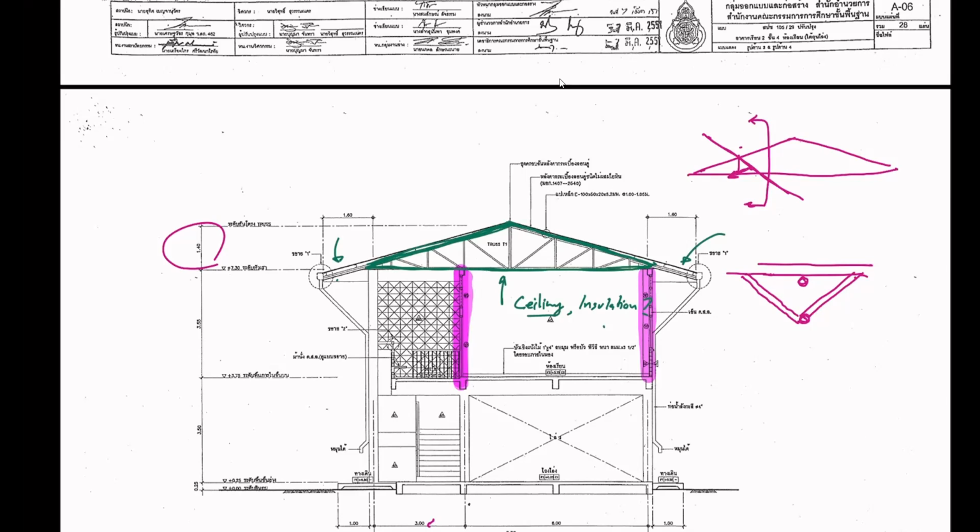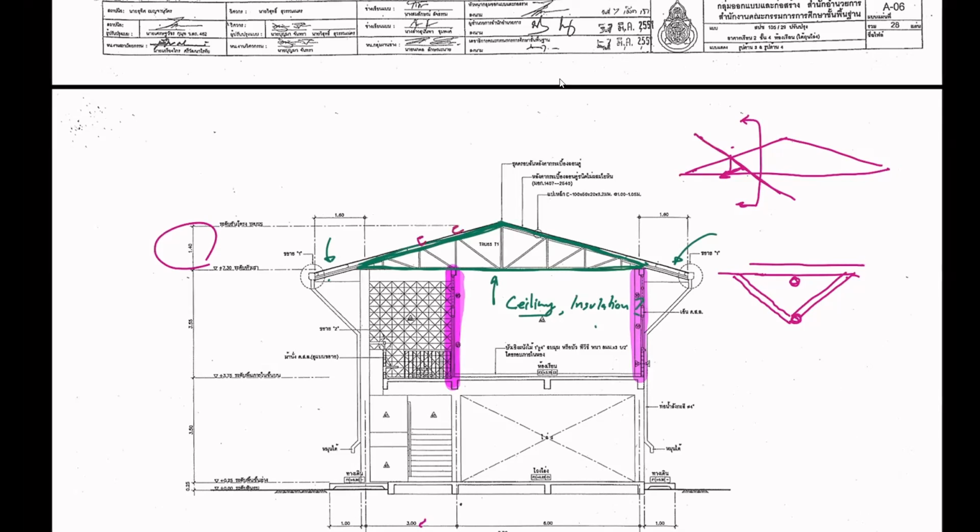I'd say it's down to the quality control during construction. They just lay down the purlins, which makes it easier for them. But theoretically, the purlins should be placed here and here and here. You see that even the drawings here are bad.